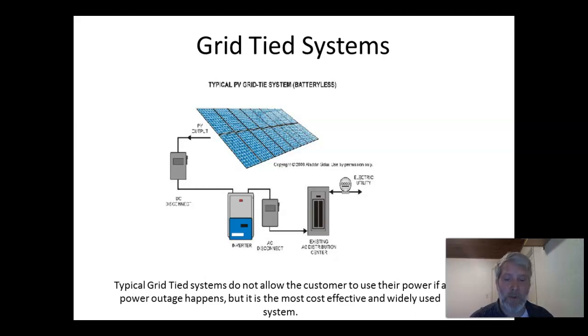That's with it disconnected. And then what we do is we tie each one of those series circuits in line with each other. So series circuits add the voltage. In this case, let's say we're at 36 volts and we go here, that'd be 72 volts, and then we would go up and up and up. By the time we do that, all of these panels are hooked in series with each other, and so they would be at roughly 400 to 500 volts usually, let's say high 300s to under 600.